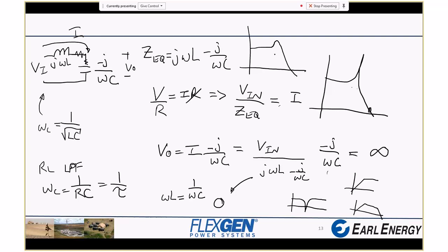What are the implications of having too large of a spike, or what can go wrong with too large of a spike? Clearly we'll have more current. Yeah, you're right. Besides the more current thing, we'll say the current is limited by the parasitic resistance. The problem can be that with very little input, you can have just a white noise input of voltage here, and since the gain to that white noise is uniform in frequency distribution, at some point that white noise will excite this resonance and give you output when you didn't expect it.